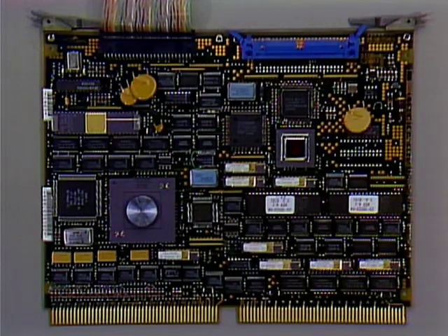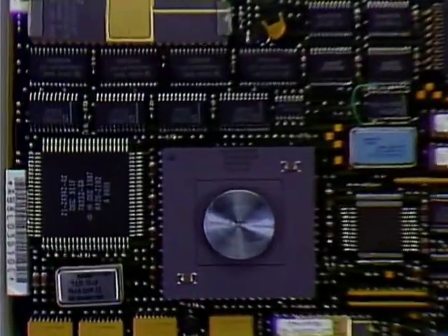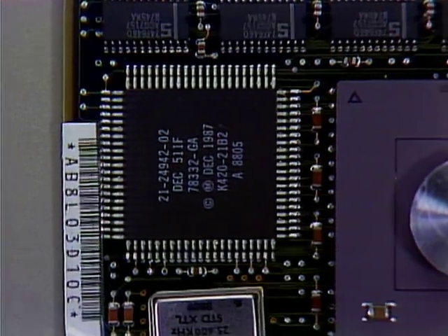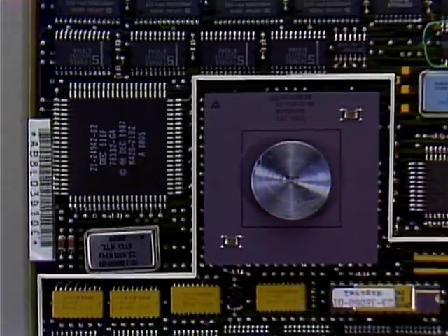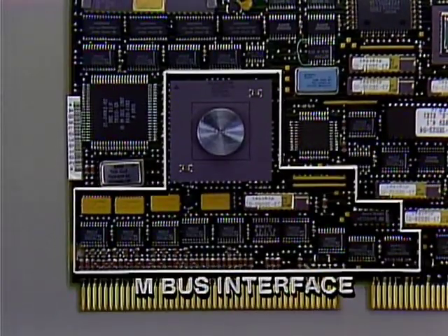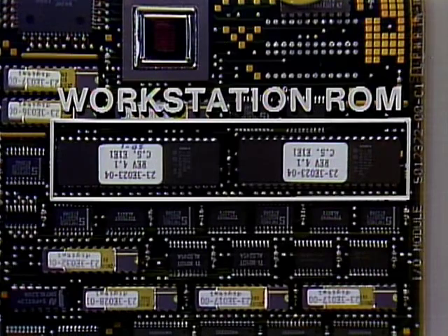In addition to the I/O device controllers, this module has a system support chip that includes a time-of-year clock, interval clocks, and a battery backup RAM that stores workstation configuration parameters. There is a PHYBIC that serves as an M-bus interface, and a workstation ROM that contains self-test diagnostics for the I/O logic and devices.